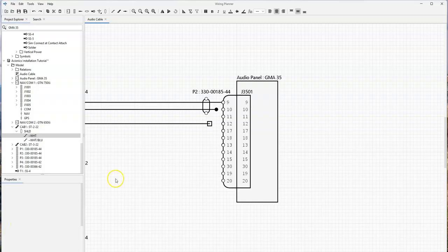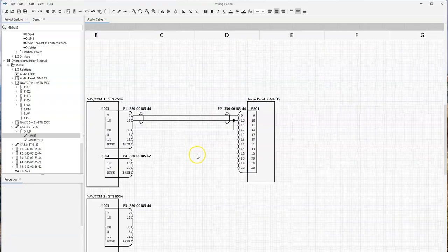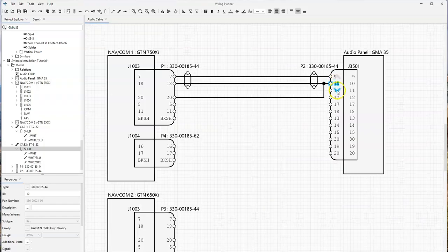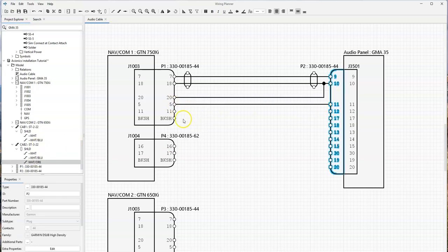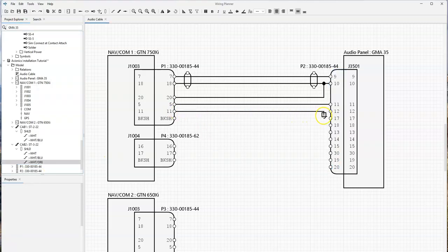So to do that, I disconnect the wire, put the terminal in place, and connect it. Then I go to the toolbar, select the conductor tool, and connect the terminal to the contact. Now I can click the end of the conductor and click the terminal, and that gives me my connection. The third conductor, same way.